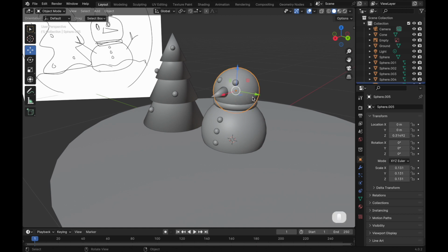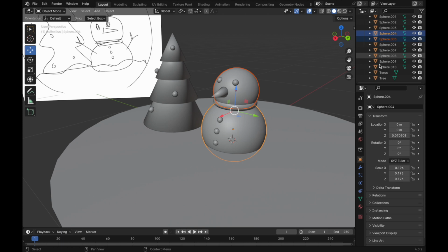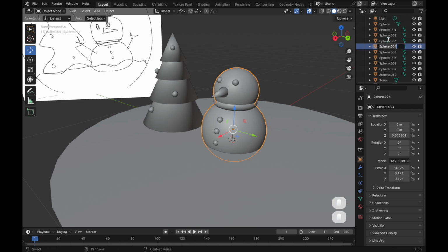Okay, now we have to name the new objects in our workspace. This makes it easier for us rather than having names like Sphere 1, Sphere 2. First, join the two spheres using Cmd+J. Click on the highlighted name on the outliner. Rename the object as Snowman.